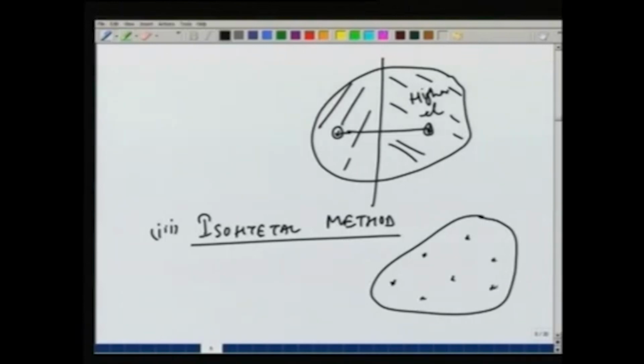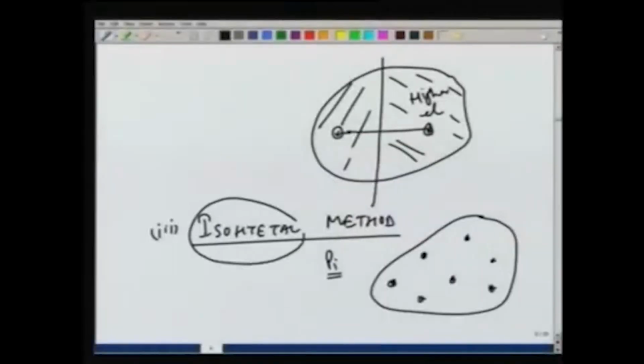So, suppose we have the rain gauges at these locations, the values of the precipitation here are known. So, at all these stations we know what are the values of P_i. Now, using that P_i, similar to contour lines which show equal elevation, we can draw lines which are known as isohyetal lines. Isohyetal lines are lines representing equal precipitation depth.